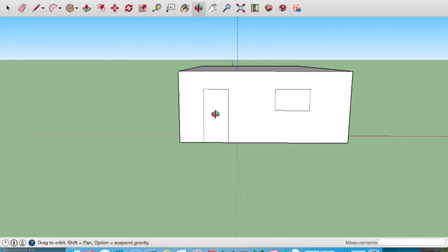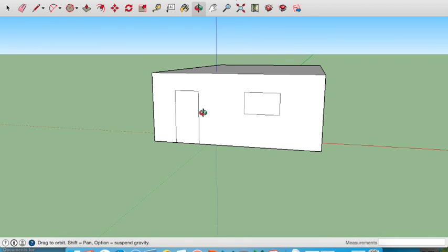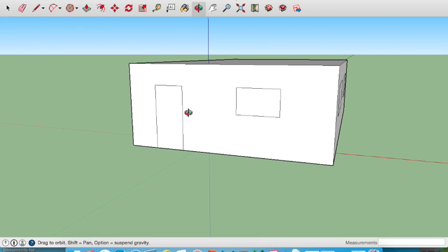And now we need to make the door and the window. So you want to make sure that you go a little to the side, and we're going to push-pull. So this button here, this icon, the square with the arrow pointing up, you're going to click on that. Now what you want to do is you want to push the door in a little bit to make an edge, but you don't want to push too far. So highlight your door. You should have it highlighted when your cursor is over it. You're going to click and just drag it a little bit. You don't want to go really far in. You want to make a very small edge. And when you make that edge, you're going to press your delete button and you have a door.